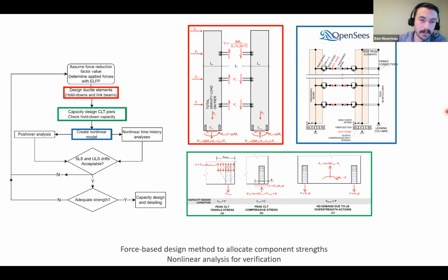Then we'll go create a nonlinear model, and that can either be one capable just of a pushover, or a cyclic test, or a cyclic protocol. So either we're going to simulate ground motions with it, or we're just going to push it over and observe the performance. I think both methods can be worthwhile, and maybe it's a point of contention during the design process for the designer and the peer reviewer to work out.